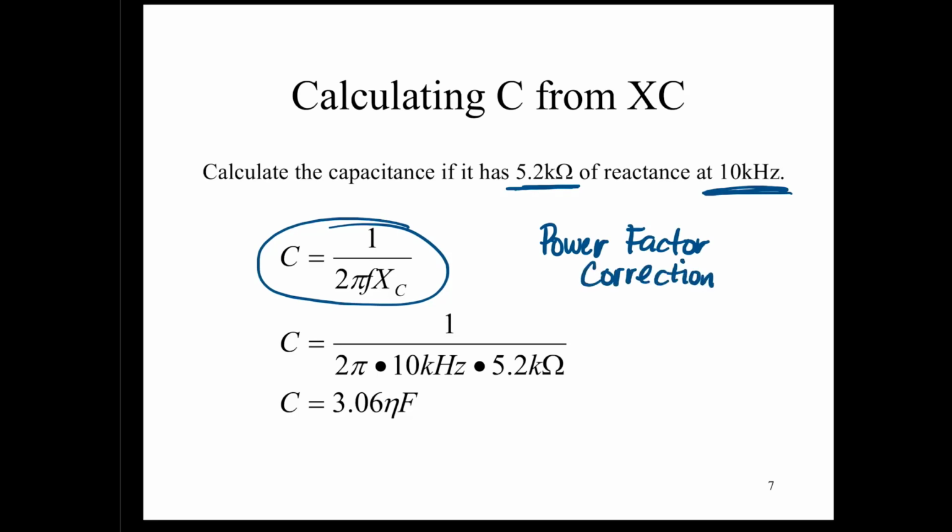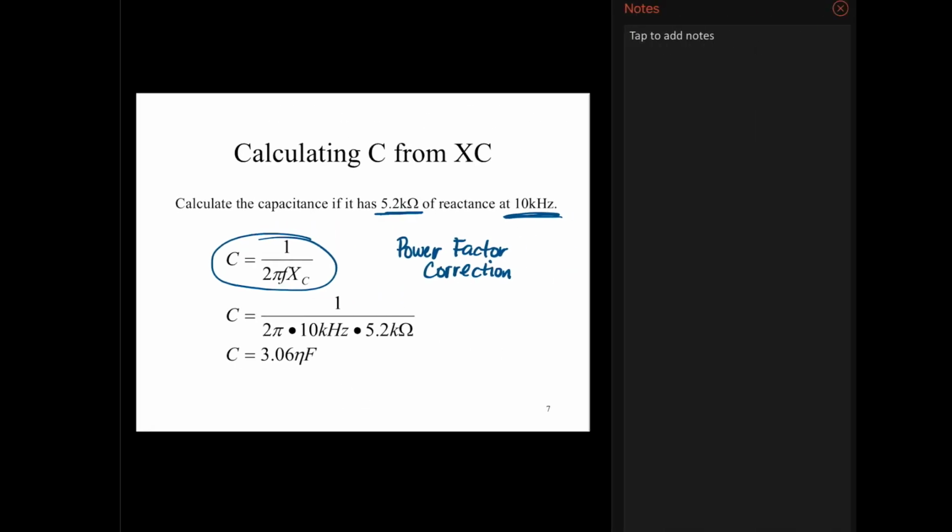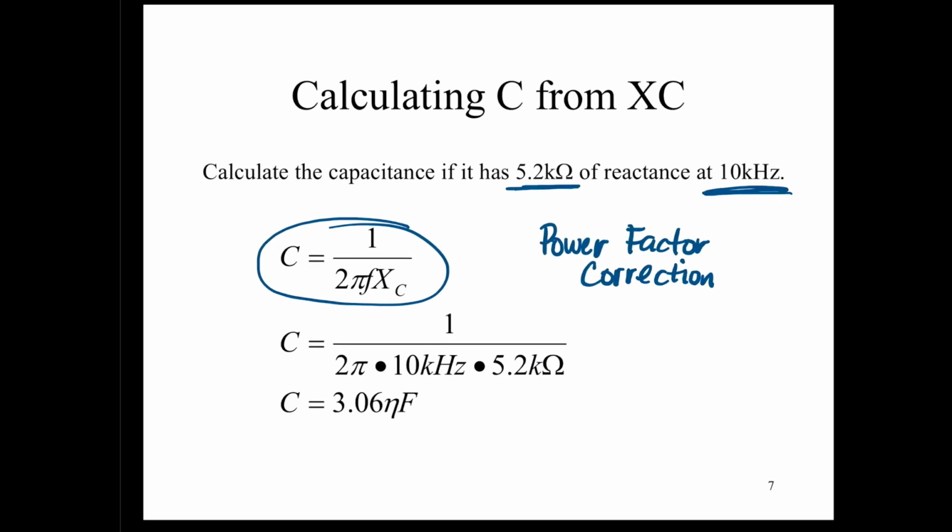Now, there's no doubt when we look at power, we'll look at that in more detail, but notice how we didn't go about this process when we were doing inductors. That's because when it comes to power factor correction in power systems, it's always done through the use of a capacitor. Think of a circuit where you need to balance the value of XL and XC, and you have a 60 hertz circuit, and you currently have a value of, say, XL of 2K ohms.